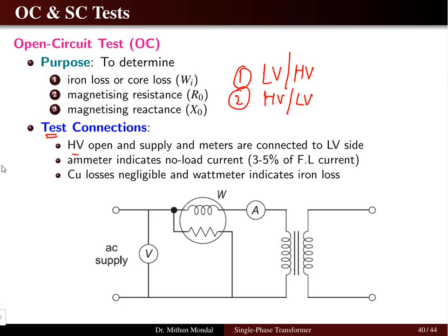We keep the high voltage side open. So if this is open, then this side will be the high voltage side. And all meters we will be connecting on the low voltage side, whether it is an ammeter, voltmeter or wattmeter.